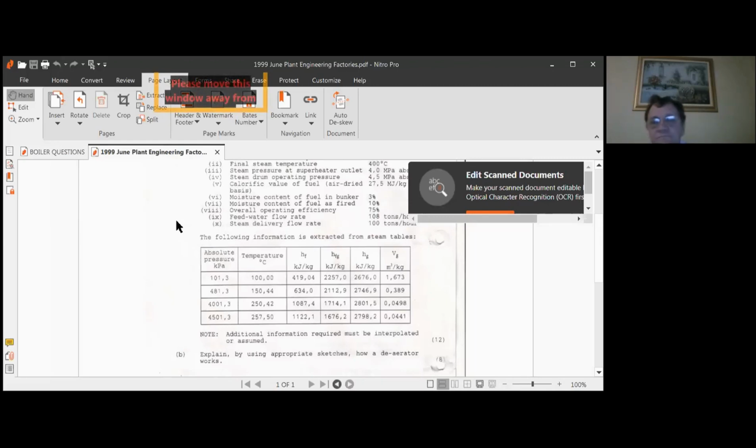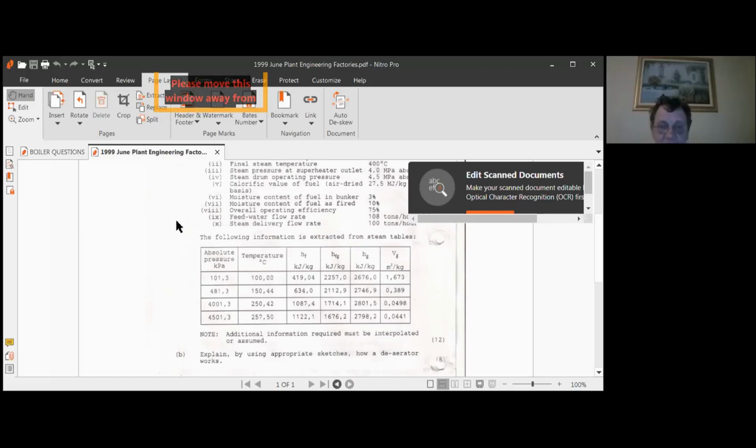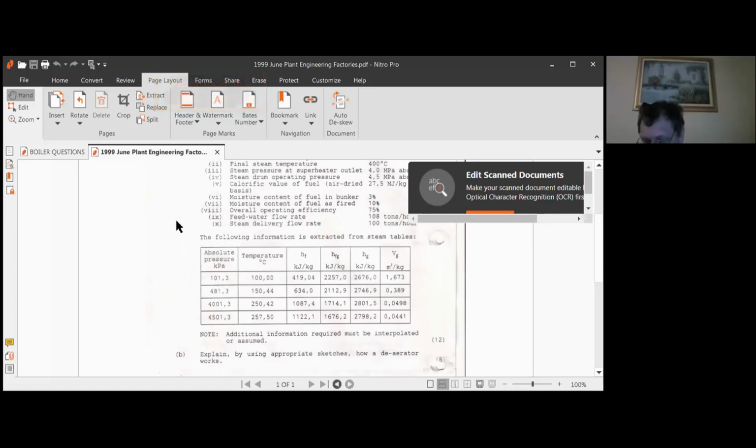Okay. There was one question I've seen, not the ones you've given us, where it says unburnt coal, so you minus it from the 100%, am I right? Yes. And so if there's moisture in the coal, you're adding it to your 100%, because I need to burn more to get the same heat value out. Okay, I get that. Thank you.